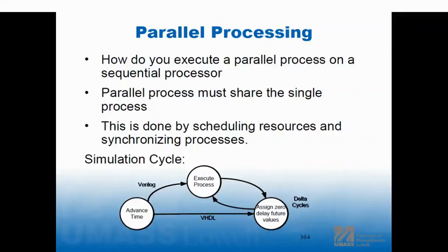I think of, and if you do any board design, this is why I hate board design. You have a power to ground short. I hate shorts on boards because they look like they're everywhere, right? Oh, power to ground shorted here, it's shorted here, it's shorted here. Of course it is, because they're shorted together. There are techniques, obviously. Well, that's what zero delay loops or combination loops are, same thing, right? Everything's oscillating. You can't figure out where the connection is.